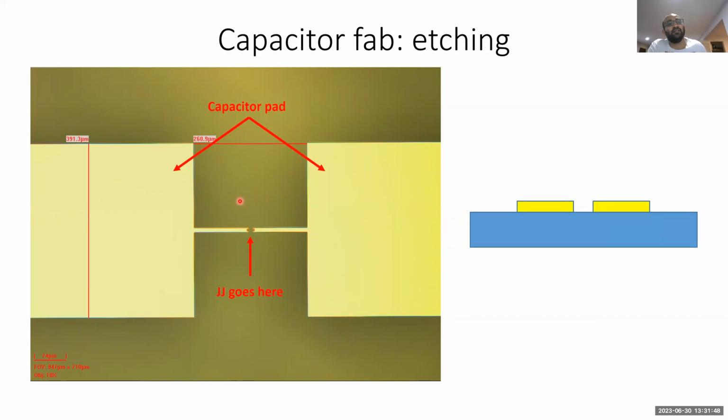So if you're etching tantalum or niobium with SF6 or CF4, you will also attack the silicon as well, and your silicon might end up being partially etched and a little more rough as a consequence. That can definitely affect the surface qualities of the exposed substrate.